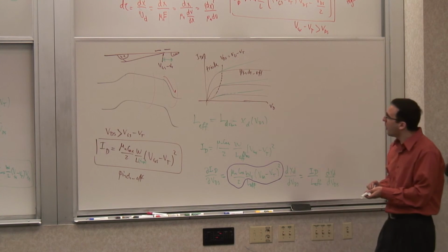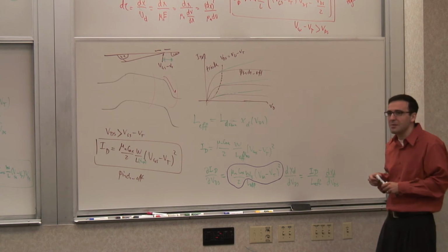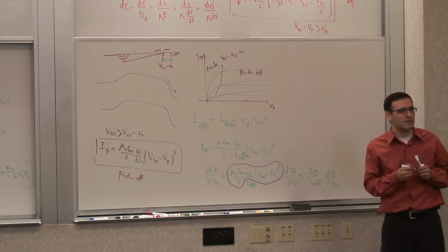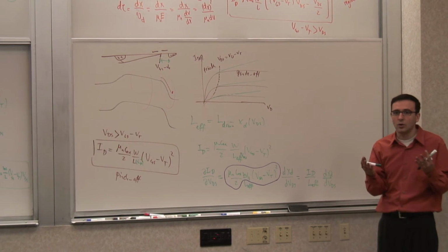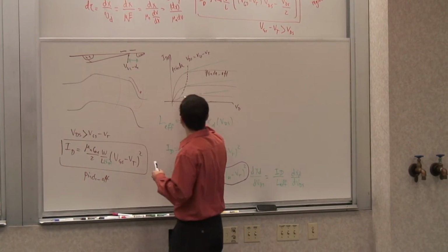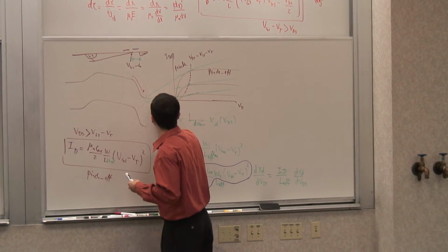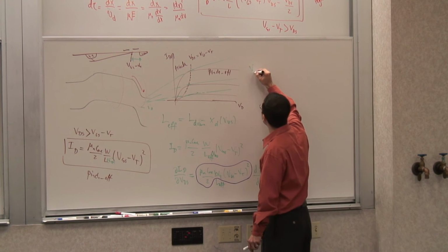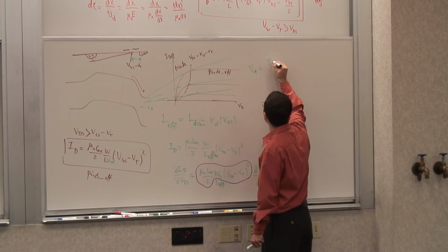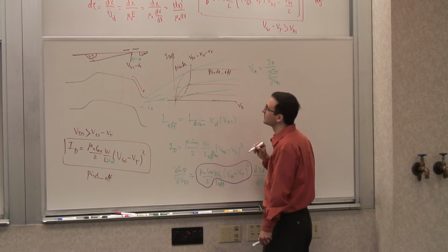Okay, fine. Now, what I need to calculate: you remember before, when I was talking about the bipolar transistor, I defined the Early voltage, which was kind of the intercept point of all of these lines, this minus VA. VA was the ratio of ID to the derivative of ID with respect to VDS.